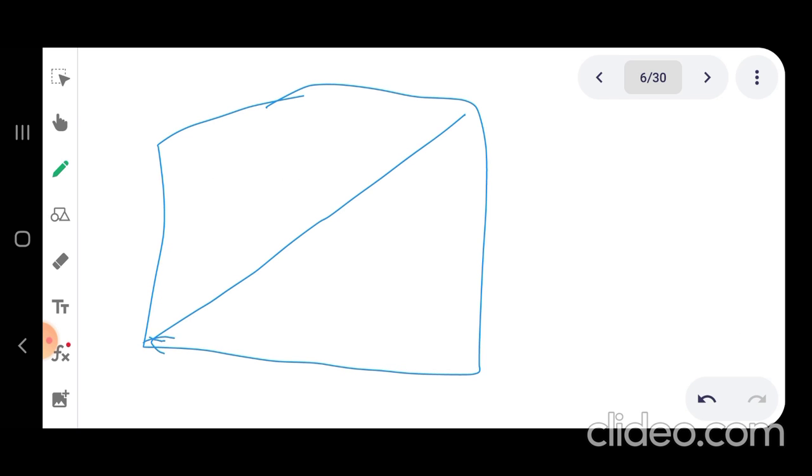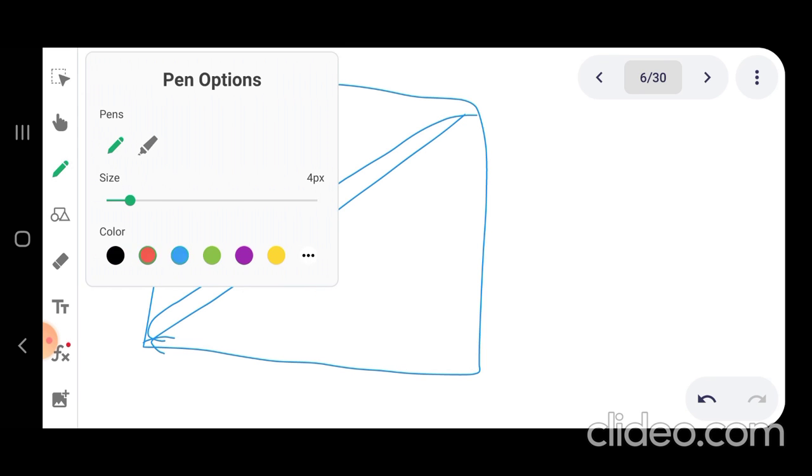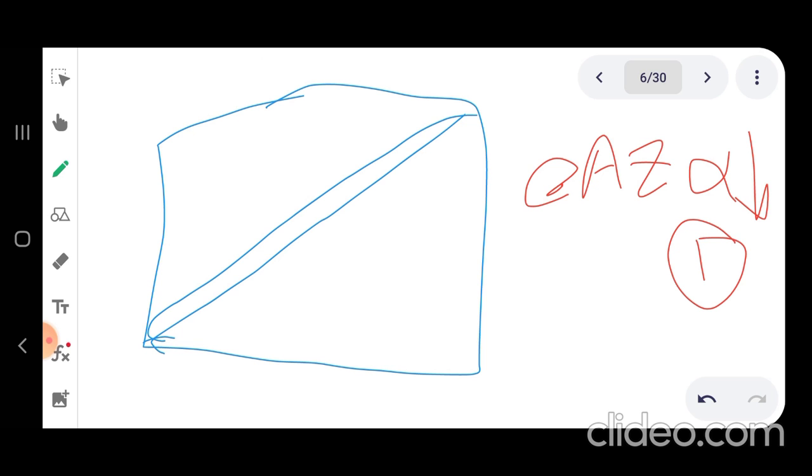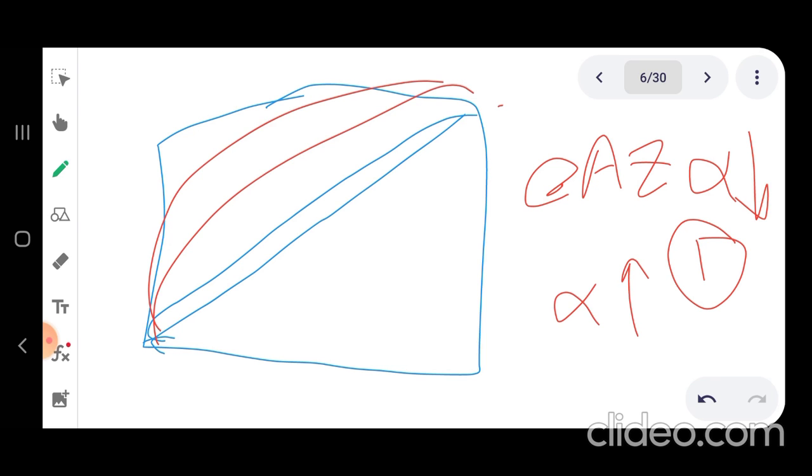You will get a tight equilibrium curve, very tight, that's very close to the 45-degree line. Why? Because at an azeotrope you will have very low relative volatility, very close to 1. In other words, it's very close to the 45-degree line. And as this relative volatility increases, you will get bigger and bigger curves. So let's say this blue curve represents the equilibrium curve for the azeotrope.